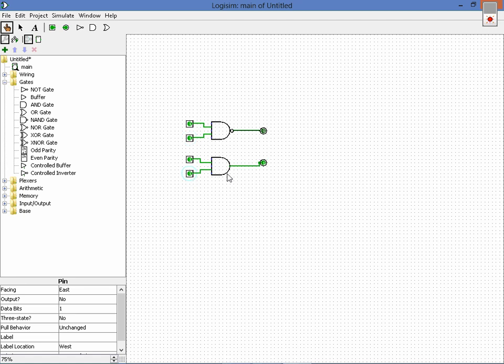But we can see the behavior between the AND and the NAND is exactly opposite, where the NAND, by default, if my condition is not met, is going to have a value of 1. The AND, if my condition is not met, has a value of 0. And then when my condition is met, which means both inputs must be a 1, the state changes.